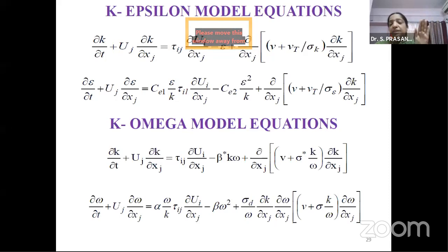The first basic governing equations that any model uses are your continuity, momentum, and energy equations wherever applicable. And the second is, in order to know about the average properties of the flow, we have applied Reynolds averaging to these Navier-Stokes equations, which has given us the Reynolds-averaged Navier-Stokes equations. That made us encounter a new sort of parameters called Reynolds stresses, and those stresses are solved using these models in order to have a closure to the problem. Whenever we apply a model, it is called closure to the problem, in order to solve these additional parameters that have been encountered.